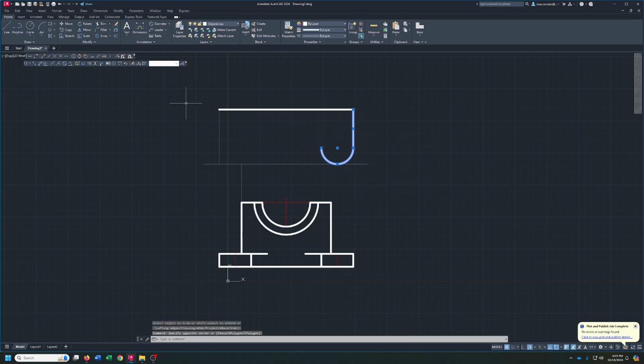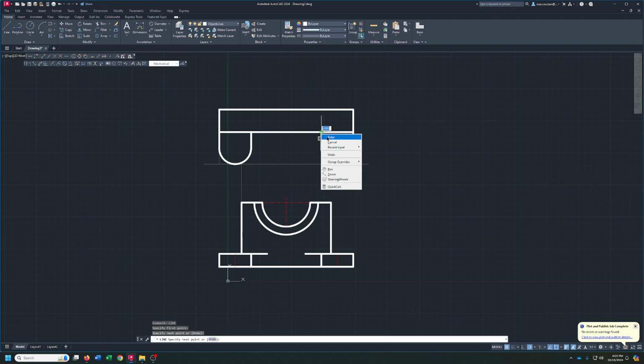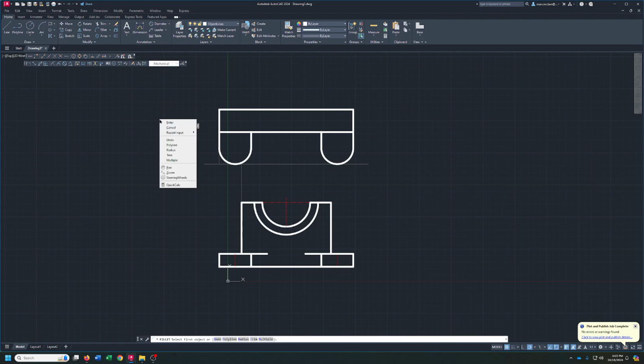I'm going to grab that and mirror it to the other side. And once again hit no. Now this is going to offset 1.75 forward, so we'll offset 1.75. And then we're going to draw a line here and here. Now, do my fillet, right click, and the radius is 1.25.